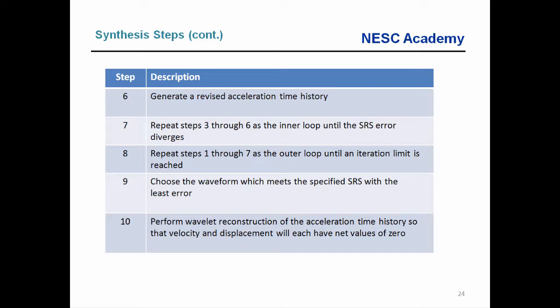Think to yourself, you've got 2 points on that component, and each of those has these very high absolute displacements due to that ski slope effect. You might think, well, they both have the same ski slope effect, so if I subtract the absolute displacement at point A from the absolute displacement at point B, that will give me the correct relative displacement, and I don't even need to worry about the ski slope effect. That just all comes out in the wash.